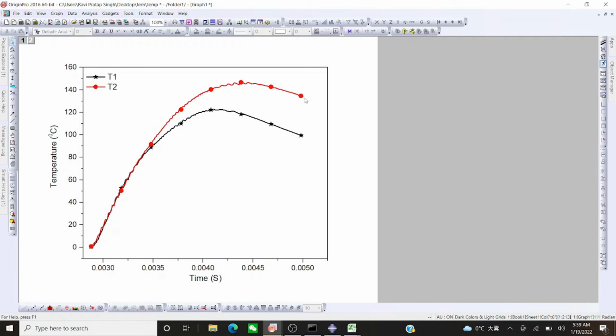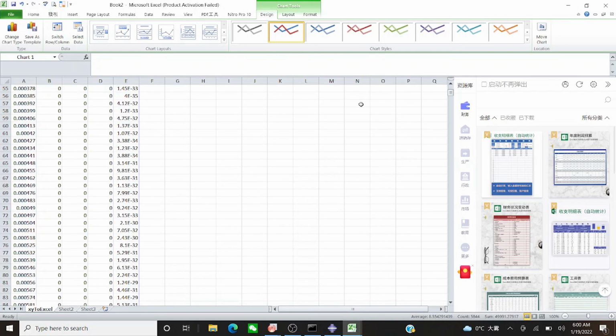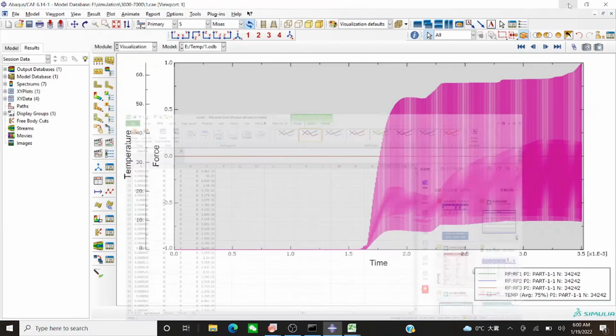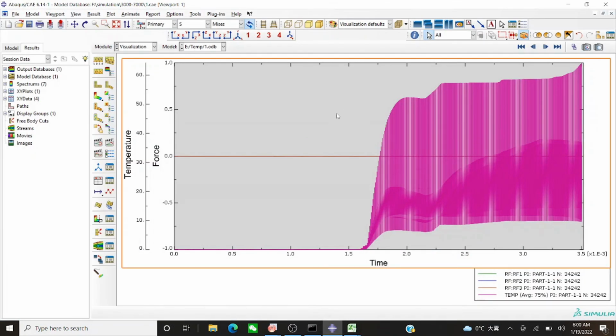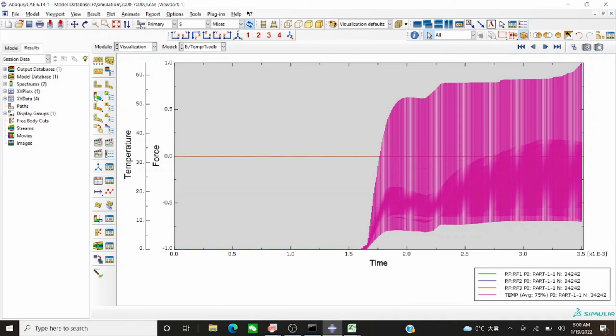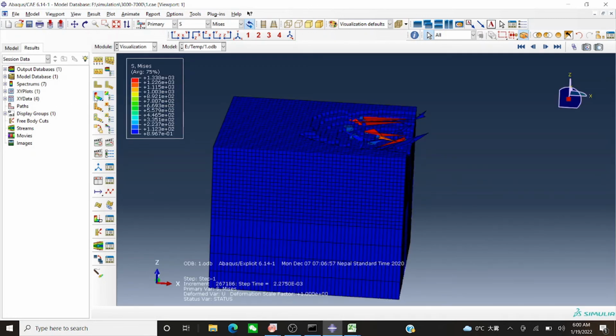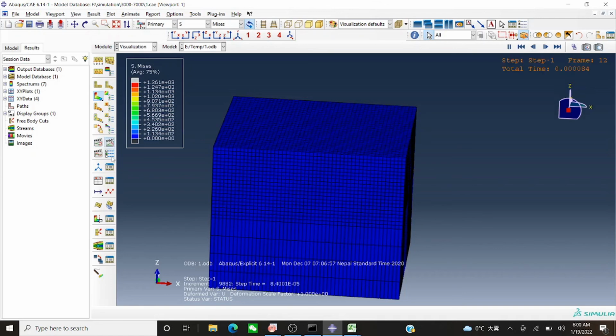And this was for a very short period. You see the time period was 0.004 second. So the time period was very small, so heat flux is generated for a very small time. You have to make sure to catch that peak time during manufacturing, because it can really hamper your material surface during manufacturing.